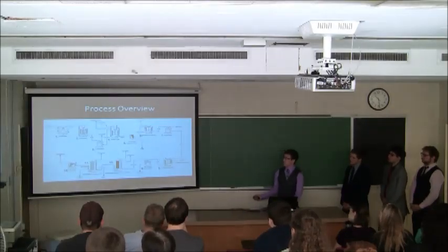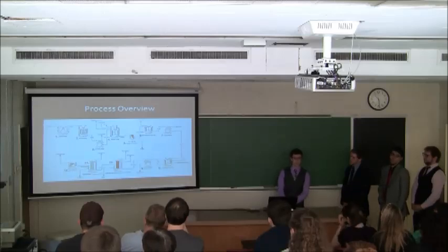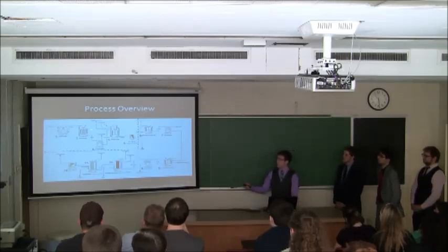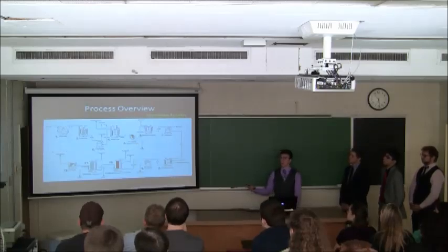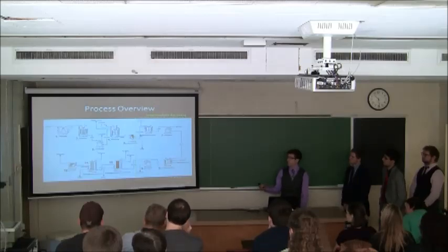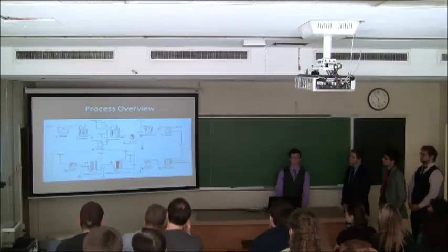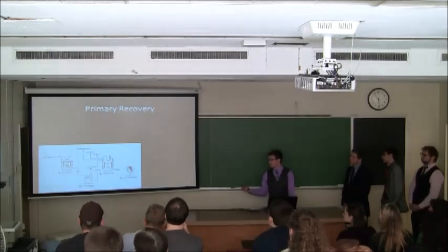So this is a process overview of what we designed using SuperPro Designer, which is a process design software. We began with primary recovery, from fermentation to dead-end filtration. Intermediate recovery, which included 2 precipitation steps to obtain the plasmid DNA. And then final purification using chromatography. So I'm going to go a little more in depth about each step.